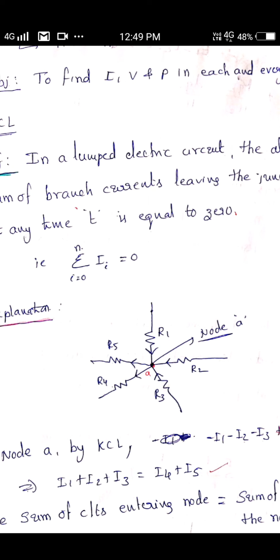Now see here, I assumed that through some branches currents are flowing out, and through some branches currents are entering. What definition is given at any particular time? Because at that time maybe 5 loads are connected at that node. Maybe after some time some loads may be disconnected. Loads are nothing but, in our home, electrical appliances like fans, tube lights, mixie, washing machine, TV. All the electrical appliances come under load. Assume at that time you are using 5 loads, so 5 loads are connected. After 1 hour somebody may switch one off, so 4 loads. That's why we apply KCL only at any particular time.